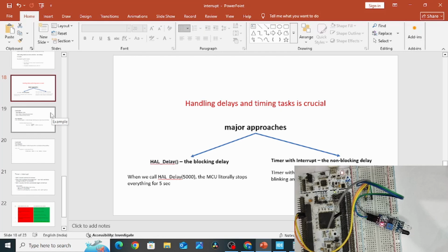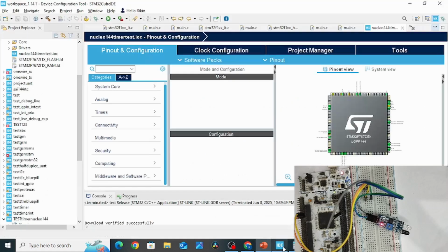But with the timer interrupt, we can achieve this with an ongoing process. Our ongoing process is continuously executed, and along with this the timer will also continuously count. Whenever you reach a particular period, let us say that particular quantity is continuously available for 5 seconds or 10 seconds, your controller will generate the required action. Along with this, your ongoing process will not be affected, right? That is the overall idea.